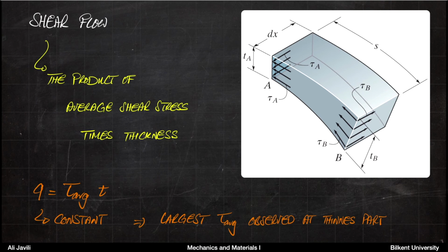Now, also you can imagine that instead of showing the shear stress distribution, you can assume that the stresses can be replaced by some sort of average shear stress, because we may or may not know the exact distribution of the shear stress. But also you can imagine that the distribution is possibly very uniform. So if you assume that the shear stress is almost uniform, you can replace it by an average without loss of generality.